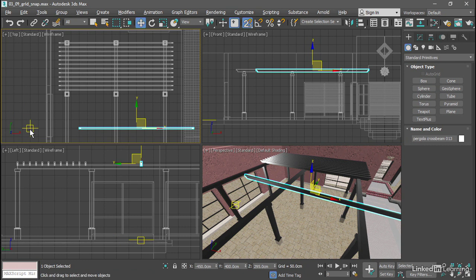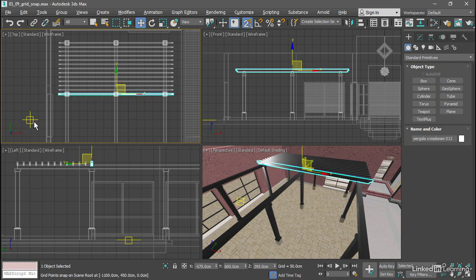This indicates the orientation of the world coordinate system, and we see X and Y, X pointing to the right and Y pointing upward towards the top of the screen. And Z is just a letter Z. Z is pointing towards and away from our current viewpoint. And when we snap in 2.5D mode, we're snapping in these two dimensions, X and Y, in the top view, but not in the third dimension, not in Z. The snap cursor maintains a constant elevation if we move an object in 2.5D mode in the top view. All right, I'll undo that movement with Control Z.